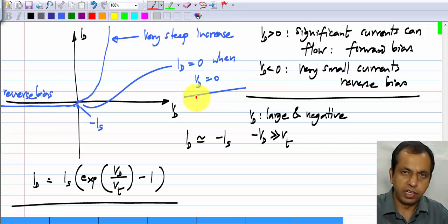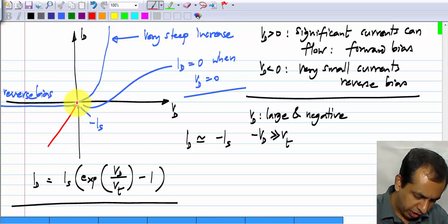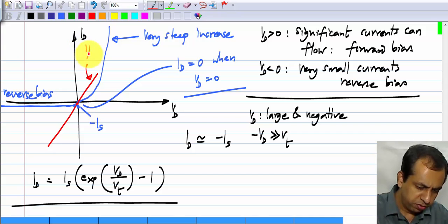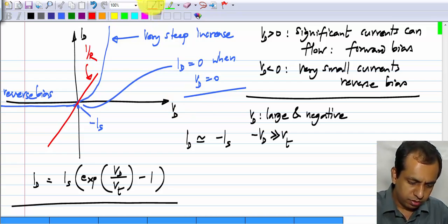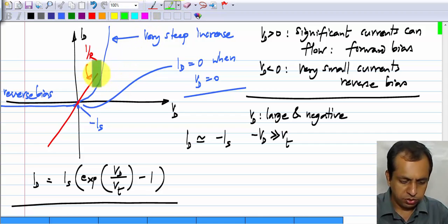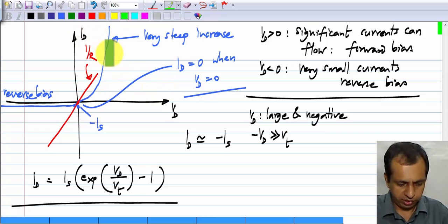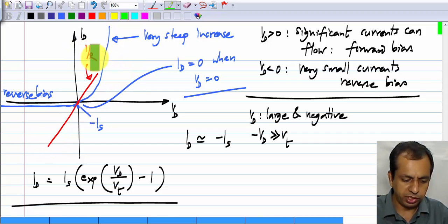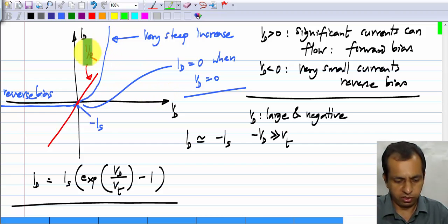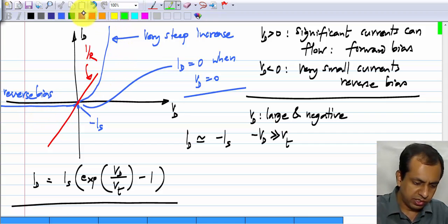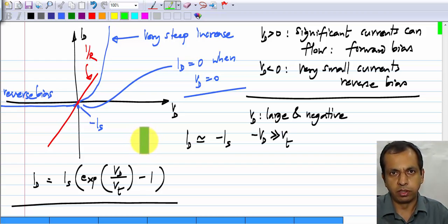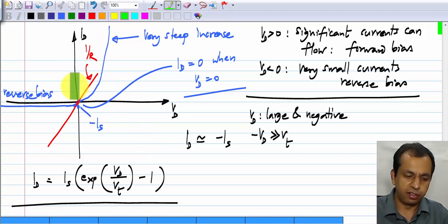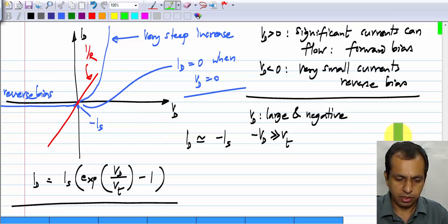We of course know that a resistor's characteristic would look like this, right? It will be a straight line passing through the origin, and it will have a slope of conductance or the reciprocal of resistance, and it is passive. Now, you must know this from your basic electrical circuits courses. If the IV characteristic of a one port or a two terminal element is in the first or third quadrant, it is dissipating power, because V times I is positive. Here in the first quadrant, both V and I are positive. In the third quadrant, both V and I are negative. So in both of these, it will be dissipating power. And in these quadrants, second and fourth quadrants, V times I will be negative and the element will be generating power. So if you have a passive element, it cannot have any part of its characteristic in either the second or fourth quadrants.